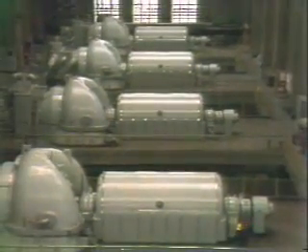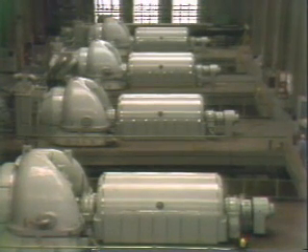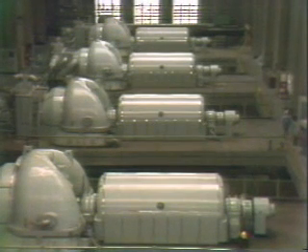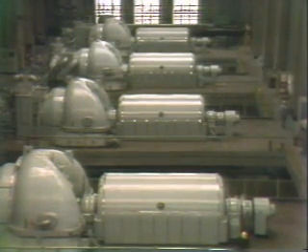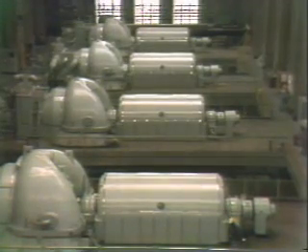In an emergency, if frequency drops below a certain level for longer than allowed by plant operating standards, the plant might have to be taken out of service to protect the turbines, generators, and auxiliary equipment, as well as the equipment of the customers served by the grid.